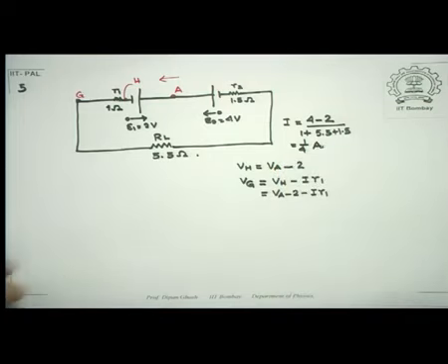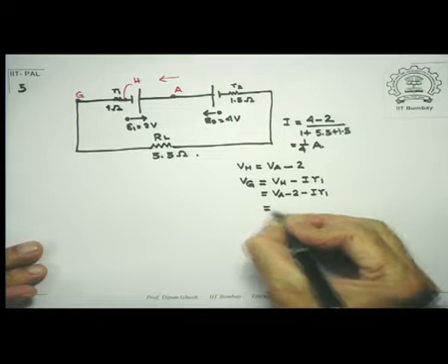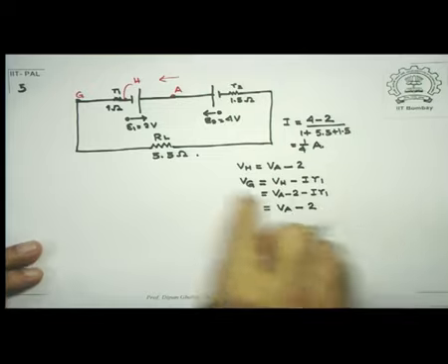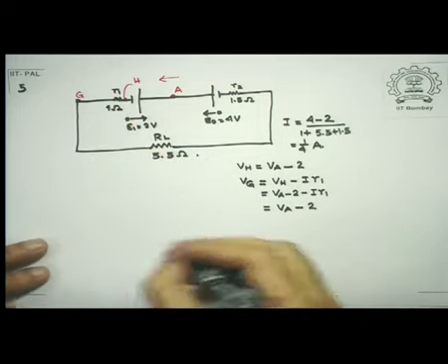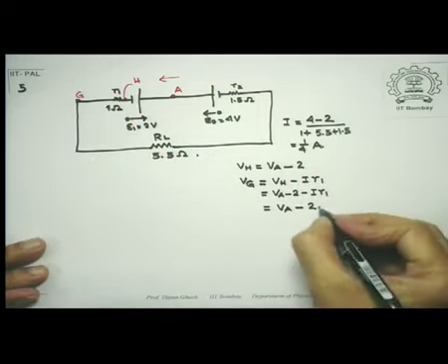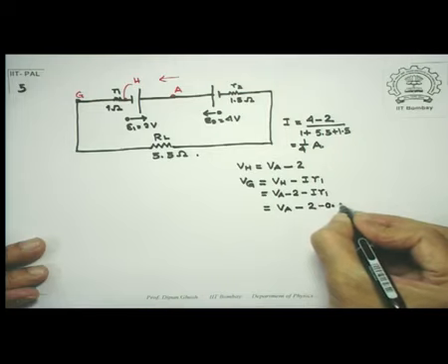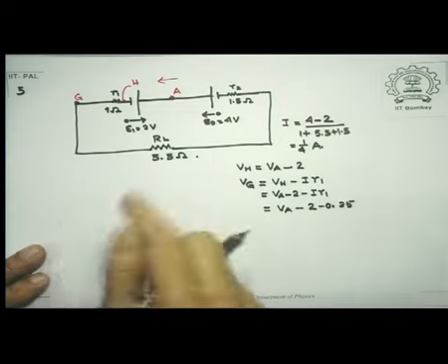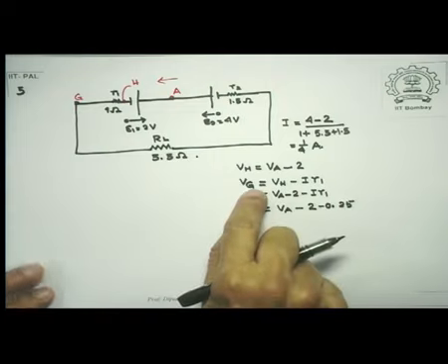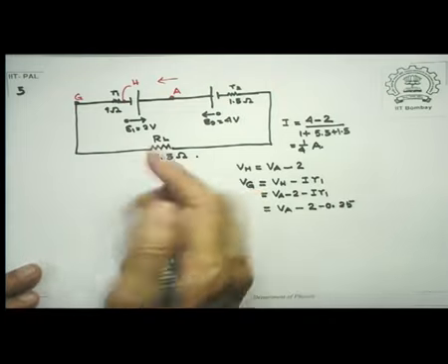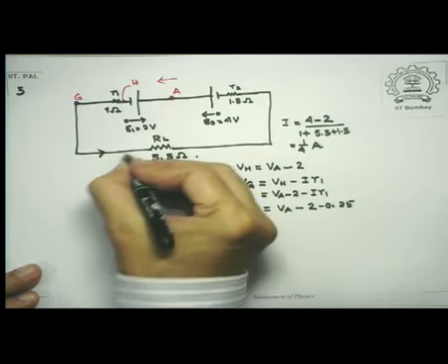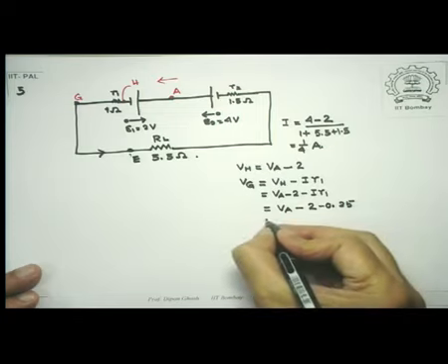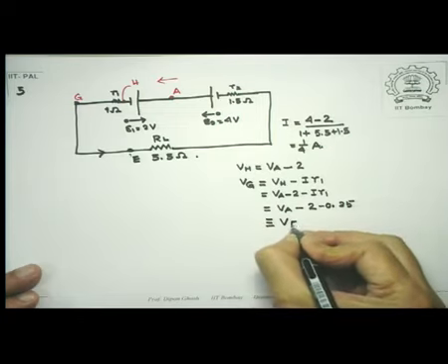Okay. So how much is this? This is Va minus 2, R1 is 1 ohm, so therefore 1 into 1 by 4, which is 0.25, and that is Vg. But then Vg is also equal to, I am going by this E, because there is nothing in between, these are resistanceless wires, so this is identical to Ve.